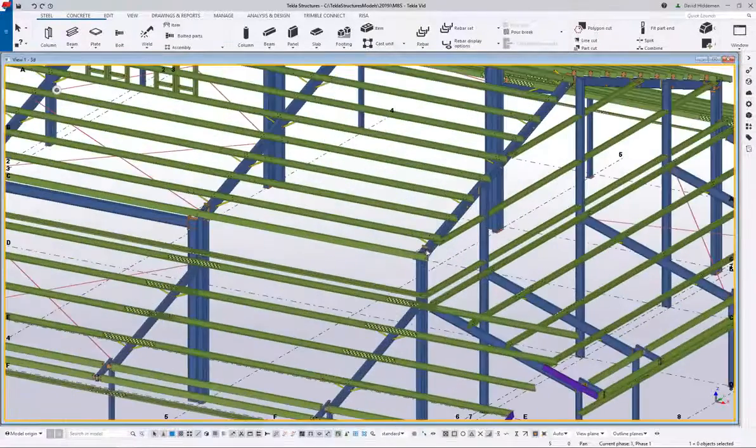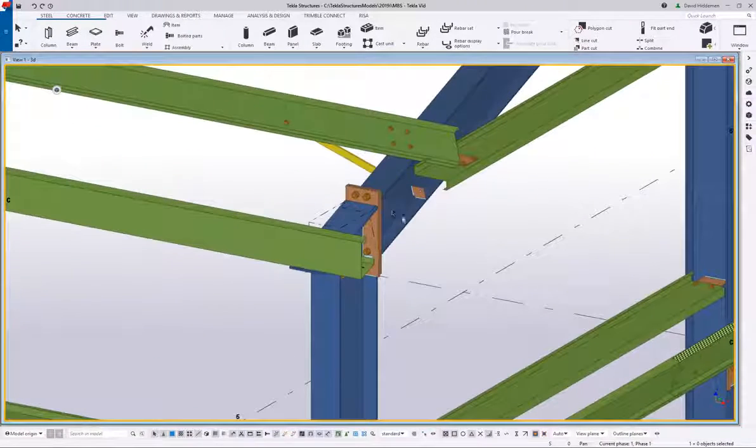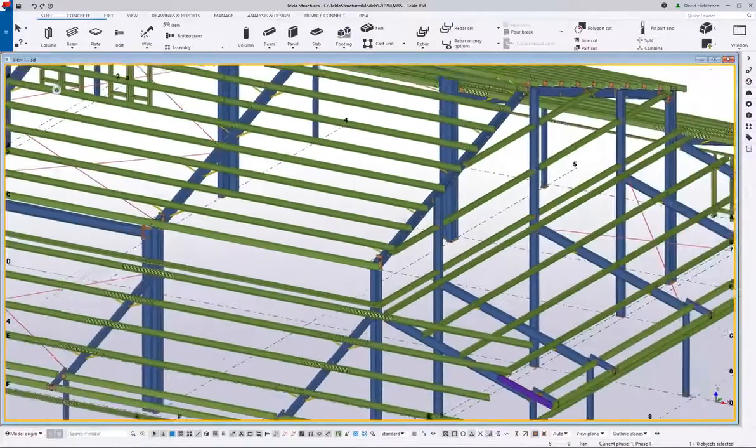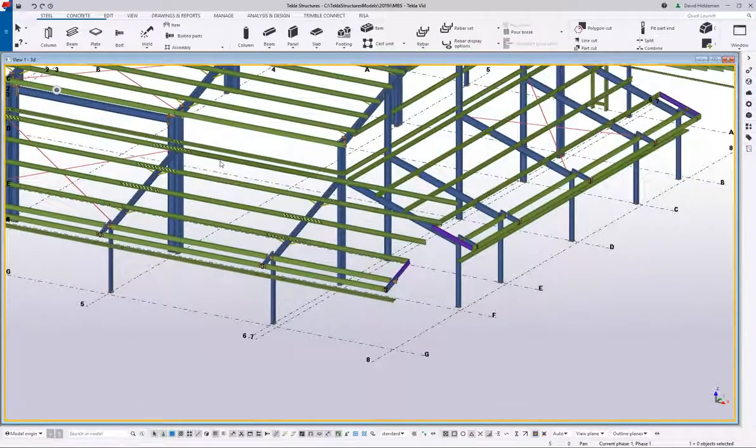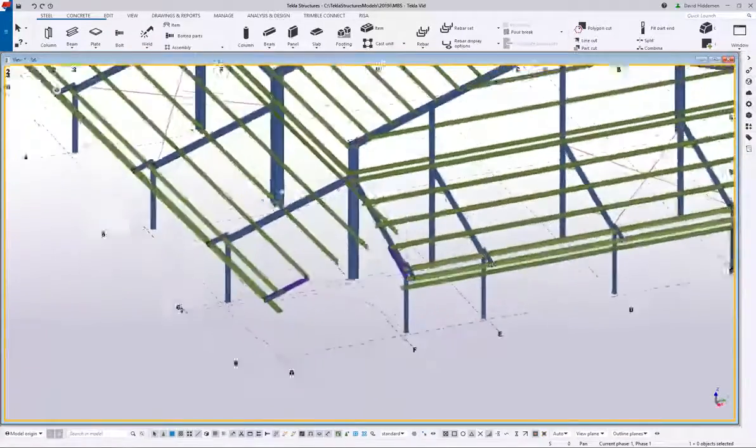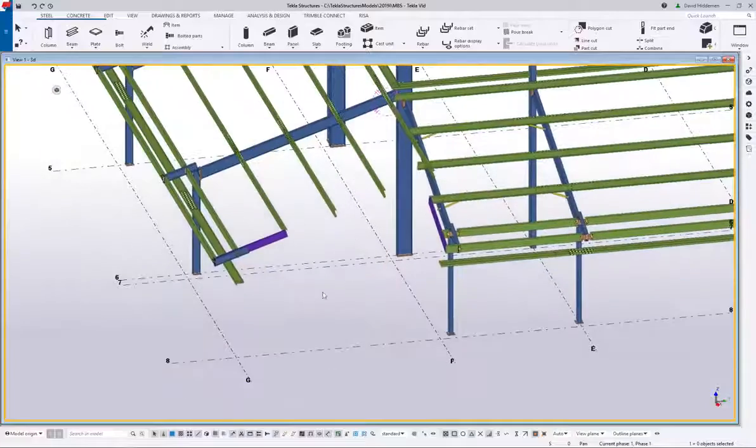So I'm just filtering things based on the name sheet. If I zoom in here a bit, we can see that the structural members have been brought in, as I mentioned, along with bolts and welds, connection material, flange braces, everything that was designed and detailed in the MBS project. Now, you may also remember that the separate lean-to structures were brought in, one going all the way out to the outside edge and one stopping short. So here in Tekla Structures is where we're going to finish the framing to create that hip condition.